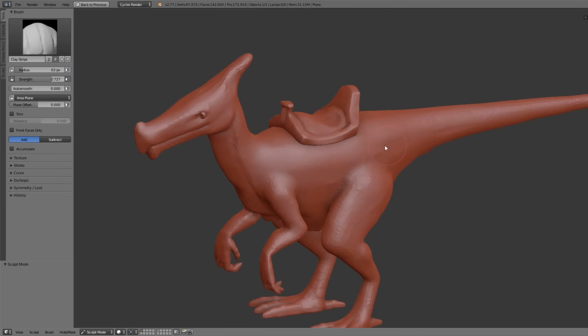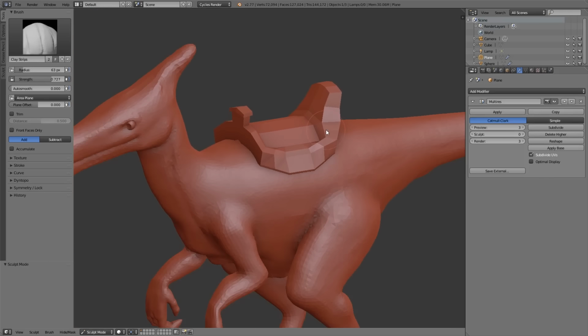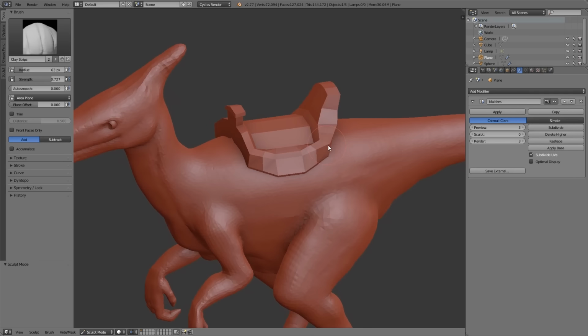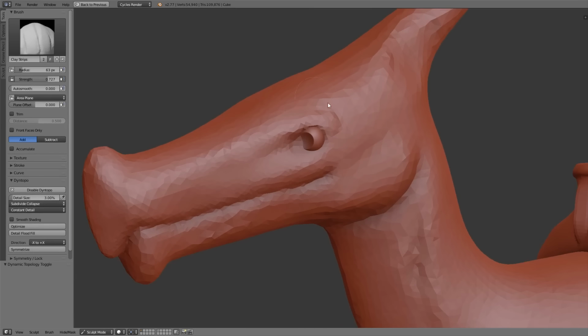And the great thing is that I can always disable or completely remove this modifier. And especially the possibility to disable this modifier is very useful when you have a lot of details in your scene. Then we can disable this modifier for the 3D view, but for rendering this modifier is still valid. That means in the viewport we can navigate smoothly, but for rendering we have the detail level of a finished sculpted model. Alright, back to the creature, not to the future.